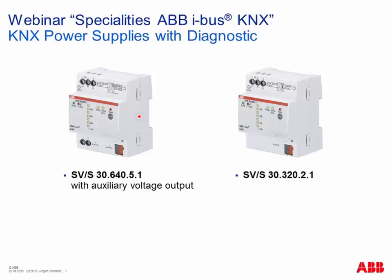Let's come to the KNX power supplies with diagnostic. We have two components here, 640 and 320 milliampere. If you look at the housing, you see it's different from the traditional KNX power supplies. We have some LEDs here, also a reset button in this example, just to visualize the actual status directly on the component. It has to do with traffic, with overcurrent, and with showing the current itself in steps. So a simple and easy way to check some main status information directly at the device.